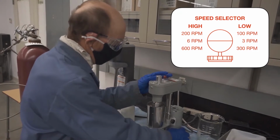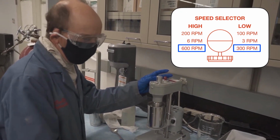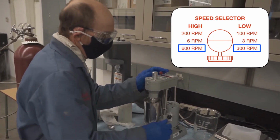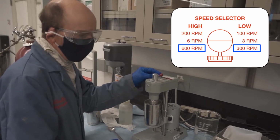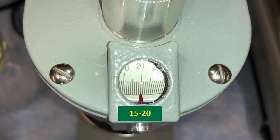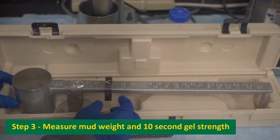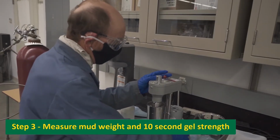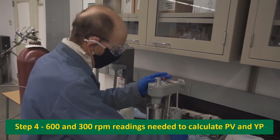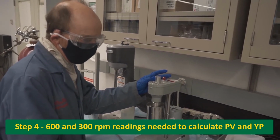Using the rotational viscometer, record the 600 rpm and the 300 rpm readings until apparent viscosity, μA, which is θ600 over 2, in other words, half of the viscometer reading measured at 600 rpm, reaches a value between 15 and 20. Measure the mud weight and 10-second gel strength of the sample when θ600 over 2 reaches the above value. The 600 and 300 rpm viscometer readings are needed to calculate PV and YP.